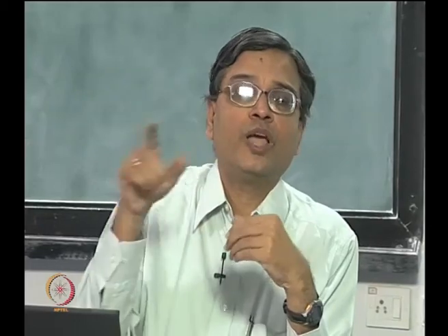You have simply connected and multiply connected problems. In multiply connected problems, you have to bring in uniqueness of displacement as an input, otherwise you cannot solve the problem. But leaving that apart, you do not put any restriction on displacement, you evaluate by solving differential equations. And when I have complex geometry, I can always go and attack the problem from a numerical approach, but the numerical approach has to be handled very carefully, because you may go wrong in understanding and implementing the boundary conditions. So, any numerical approach has to be validated by experimental inputs. Once you validate the numerical approach, they are the ideal choice for a parametric analysis.